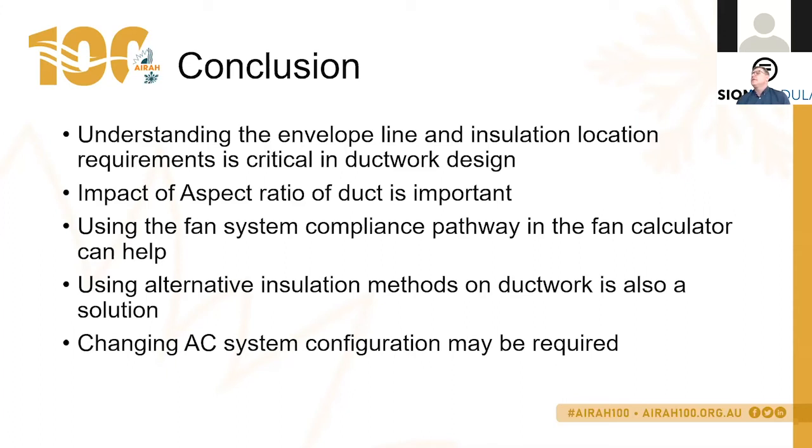A duct within a building envelope can still run into a conditioned space. Oh yes, so, it's live, done. Is the 6 metre flex ductwork R value the same as ductwork, or R1? No, so the 6 metres of flex, as per the clause, is R1.